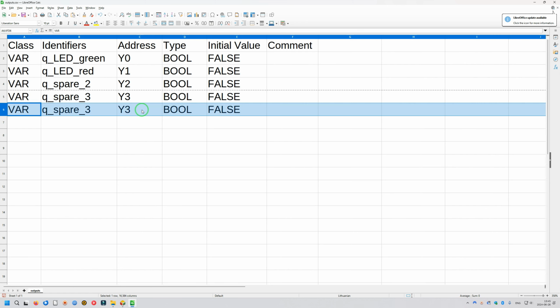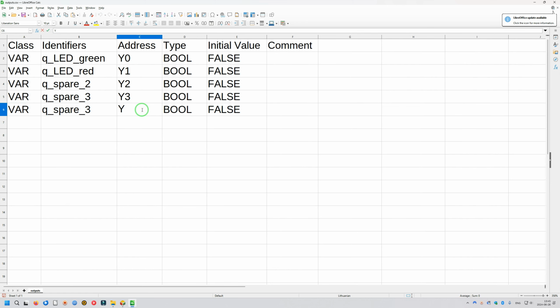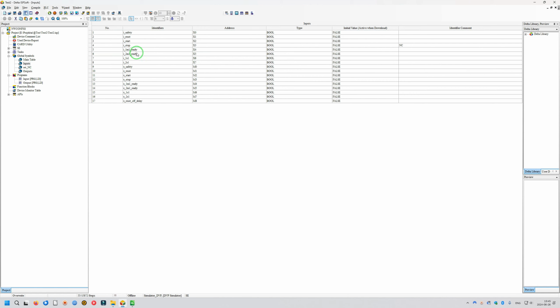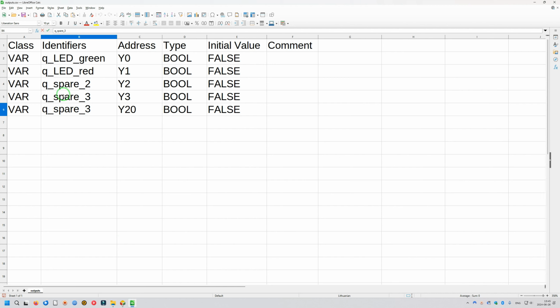And let's take, we have other registers. Let's start with output number 20. For this example, we had two motor ready signals, so I'm going to control these motors. So this will be, for example, 1M1 forward.